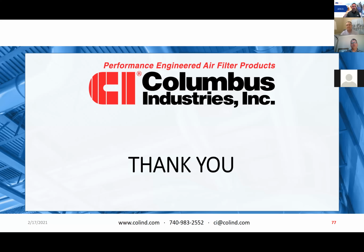But we got some that are hitting very fine, ultra fine, where we had to increase the efficiency, and we've had others that actually hit the filter almost like honey or glue hanging on this UV. And of course, it never cures. But the goal there was to keep that stuff from going up and out the stack, because if you can imagine a UV coating not curing and getting in the stack, it basically ruins the stack and the fan.